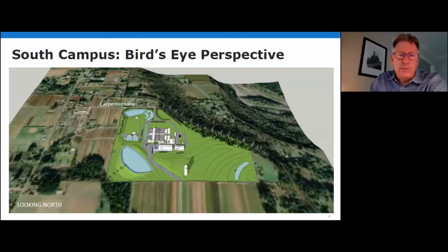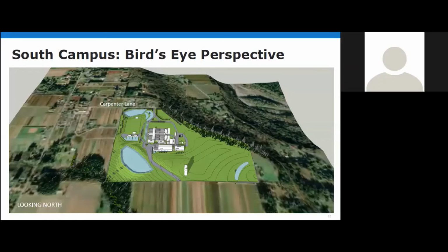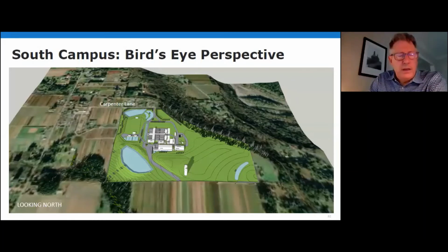If there's blowing wind and agricultural dust based on farming in the area, it may be better to have these filters covered, but it's also a big expense. So the question is, how do you weigh that expense? We've agreed to show covers over the filters on one of these options and no roofs over the other, which is more traditional in this area, to have those filters exposed to the environment.